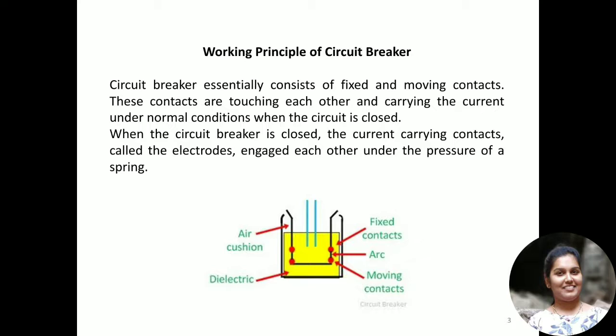After the cycle of operation of the circuit breaker, the total stored energy is released, and hence the potential energy is again stored in the operating mechanism of the circuit breaker using a spring charging motor, an air compressor, or any other means. This is how the circuit breaker working principle looks: by simple physical or mechanical pressure applied between the contacts, the circuit breaker works.